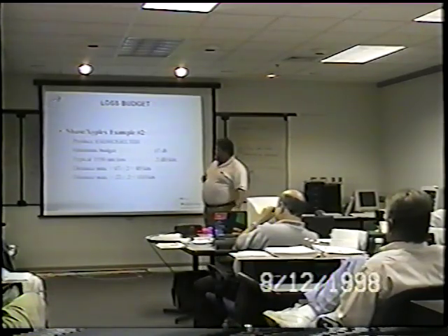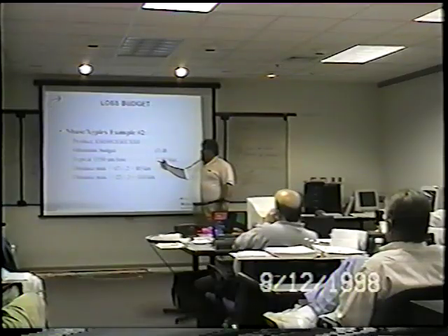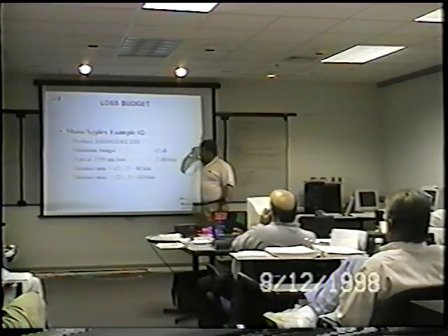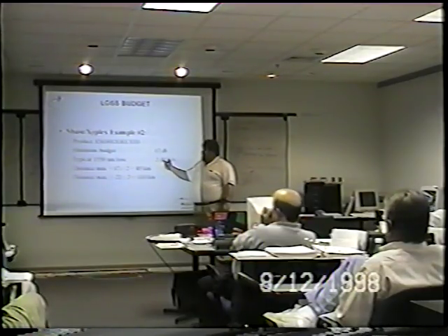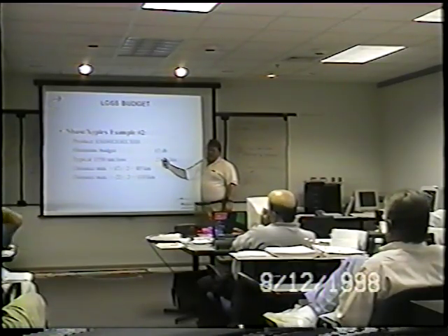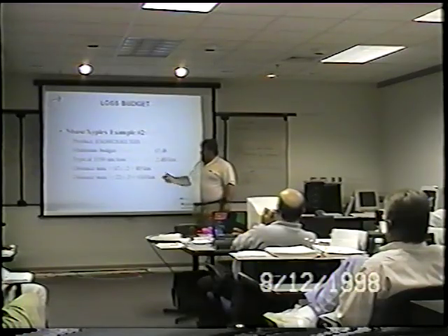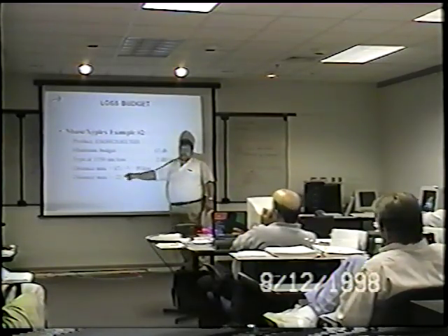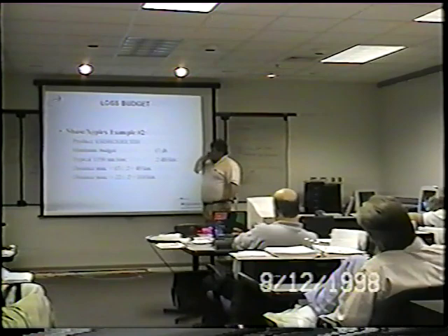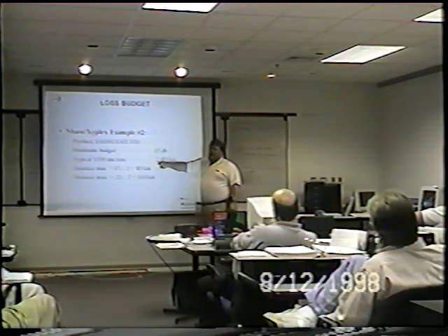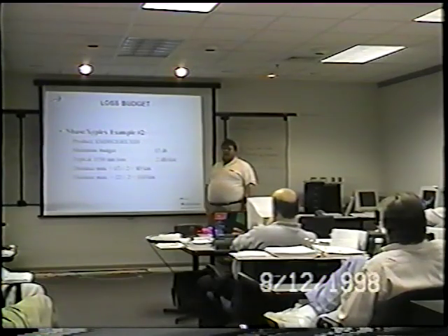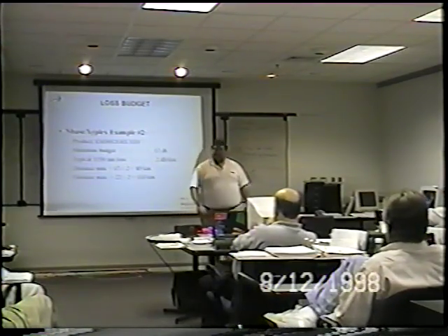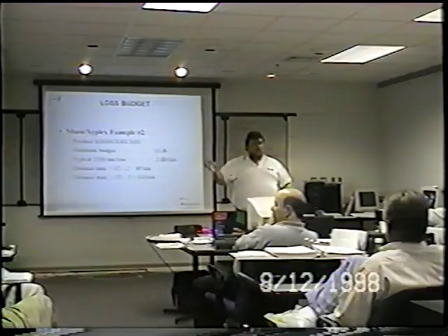Conversely, as the fiber keeps getting better, Mark and I lucked out on one. We worked with one of your SCs up in Michigan a few months ago, Ed Cott, and we based all our calculations on this 0.2 number. We were extremely nervous that we had to flirt with the high side to make sure we were going to do that distance. Come to find out, the actual fiber line came in at around 0.15 dB per kilometer, so we had plenty of headroom in terms of budget. That was the Michigan installation.